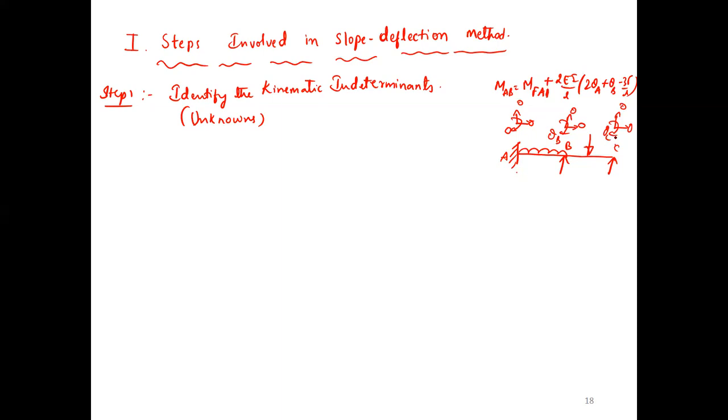Please keep in your mind, in the slope deflection method or moment distribution, whatever the displacement method, the only possible unknowns are rotations. Sway and sinking are taken separately. Apart from that, the joint displacement is only rotation. They can ask that in your MCQ. In the slope deflection method, allowed kinematic indeterminacy are only rotations, both rotations and translations, only translations, none of the above, or all of the above.